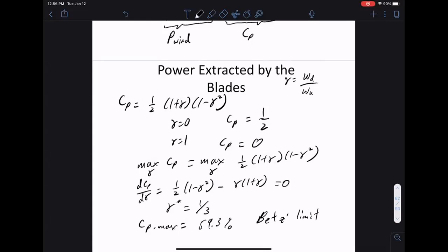So this tells you, if somebody tells you, hey, I have a turbine design that's 80% efficient, you probably should not believe that person. Believe it or not, I have heard this. There are people who try to sell me a product and they claim their design is like 85% efficient, something like that. So it's always good to have a theoretical upper bound on how efficient you can be. It gives us a number to shoot for. So this is about 60% for wind turbines. Any question about this calculation?